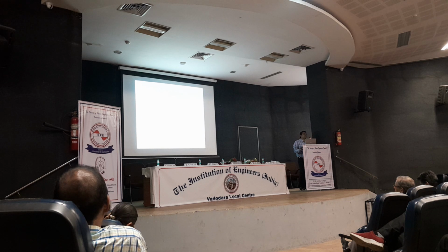When you select the fault analysis, this kind of dialog box will appear, and in this case specifically we are going to create the fault at bus number 3. So if you see the dialog box, you will find that fault location is there. We have to define the fault location, whether it is an inline fault or a bus fault, and what the fault type will be.